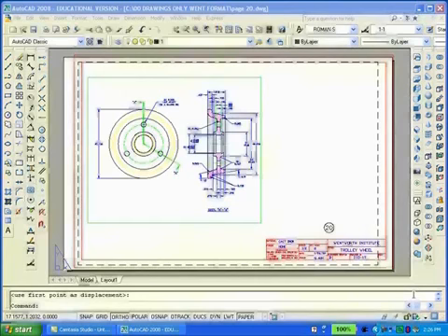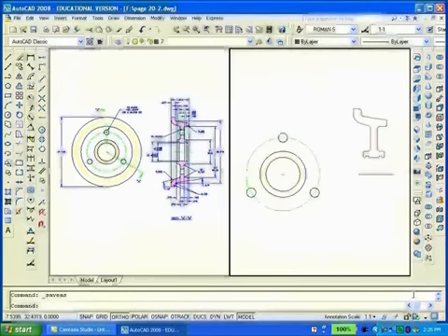This is tutorial 20, and we're going to make another solid model. This time, the profile to be revolved will be at a distance from the axis. Also remember that I made one continuous polyline out of it using the polyline edit command. Of course, I could have used the other method by just tracing over the profile with another polyline. Now I'll move into the southeast isometric view.